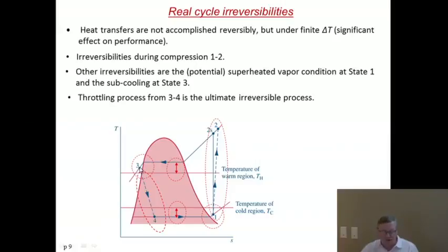And of course, the ultimate loss is the process 3 to 4, which is just a throttle that does no work at all, but it's just throwing away that potential work. Instead of going vertically, which would have given you an isentropic work, we're going sideways because it's a lot cheaper to make a crimp in a tube, which is a throttle, rather than add an additional machine.